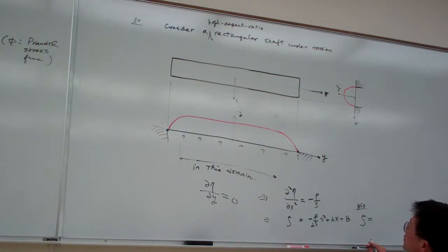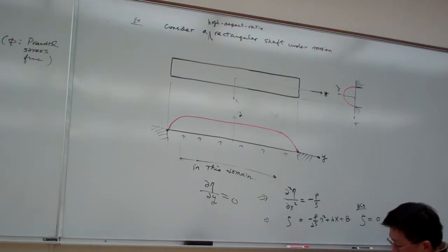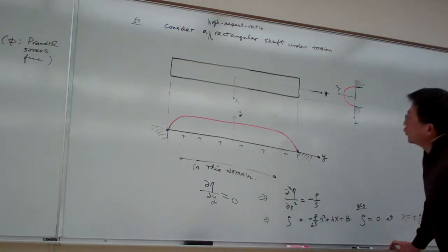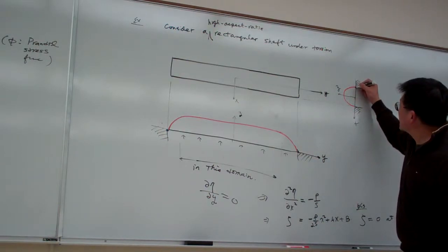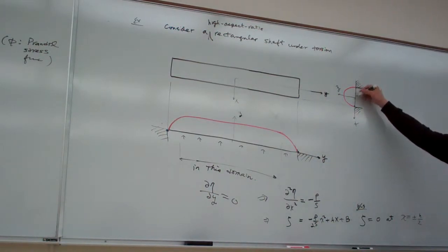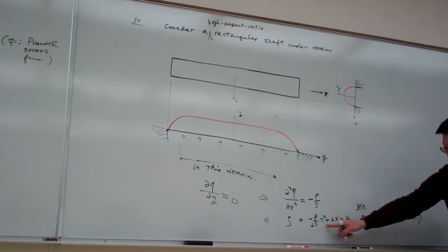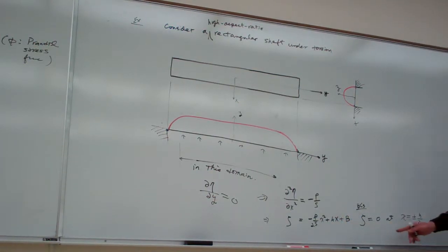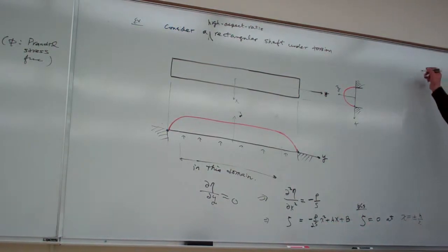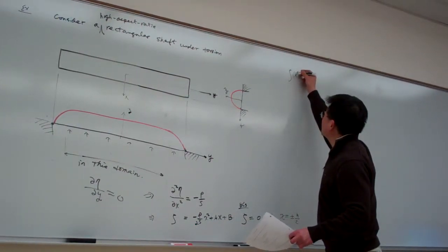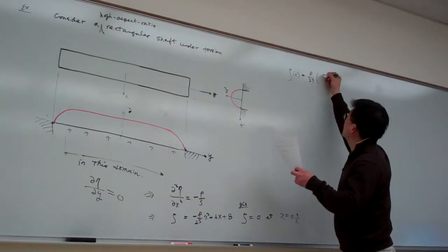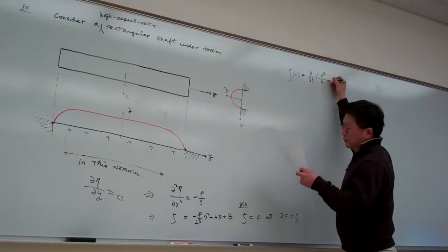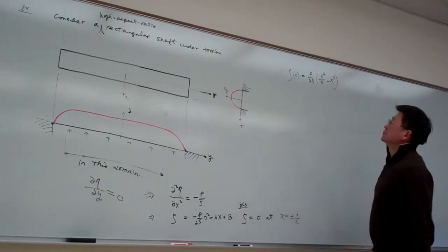This one is equal to 0 at x equal to this one here. So where is x? x is this one. You can basically see the deflection from here. This is 0, this is here. We simply apply the two points as boundary conditions because this is a function of x. We apply the boundary conditions with respect to x. So from here we can obtain phi as a function of x, and that is p over 2s times h squared minus x squared. Good?